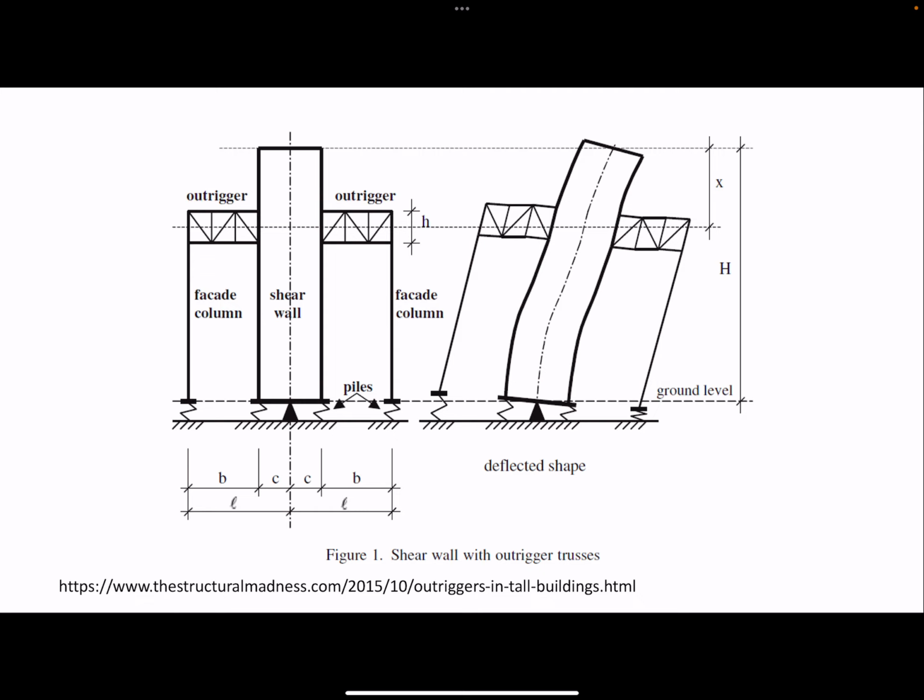For tall buildings, we typically will concentrate those shear walls towards the center of the building so that they enclose stairwells and bathrooms and elevators, right?